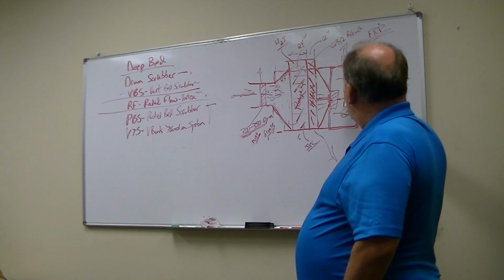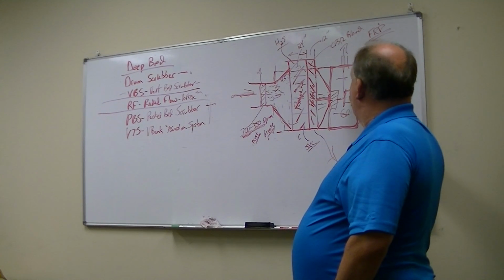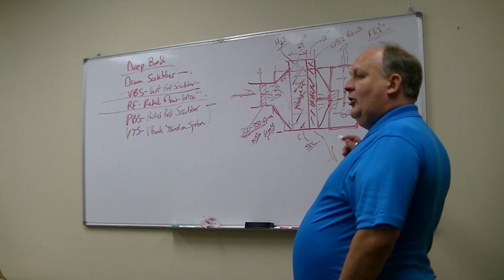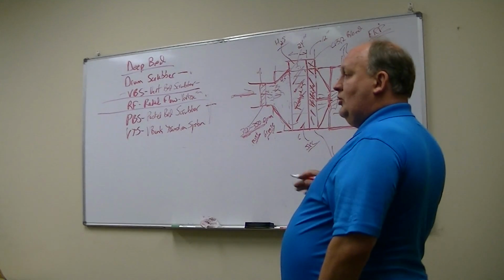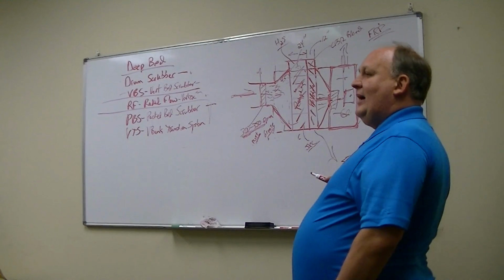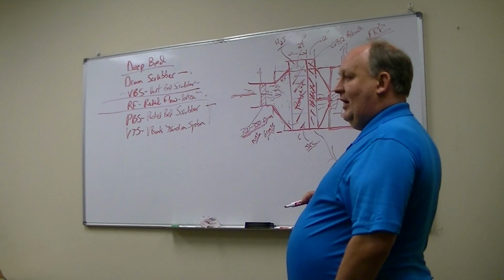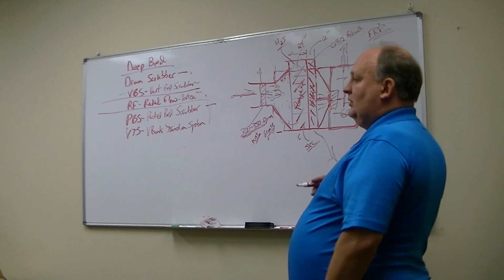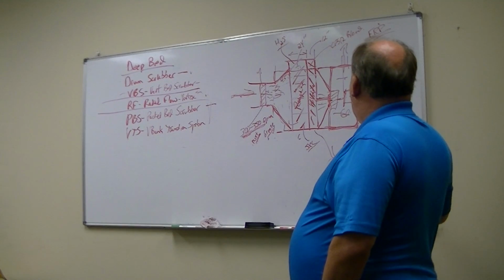The other is that these plenum fans are typically, not always, but typically direct drive. This allows you to easily attach a variable frequency drive or a speed control to that fan in order to change the airflow. So this engineer said that he wants 1,000 CFM, but you get it out to the field and it turns out we actually need 900 CFM or 1100 CFM, and it's very easy just to make that adjustment in a speed control. It's very cheap to do that as well. So this is a very nice feature.